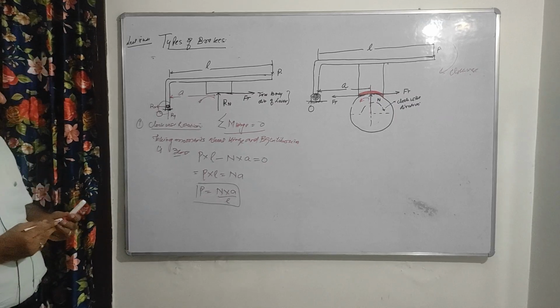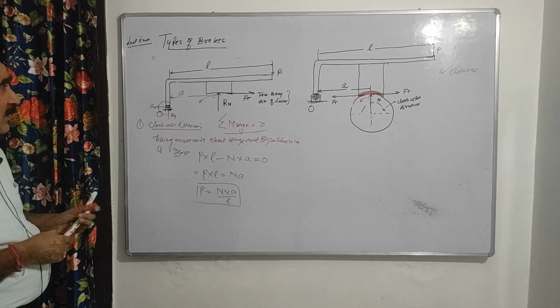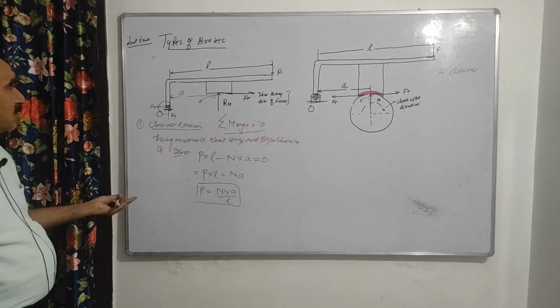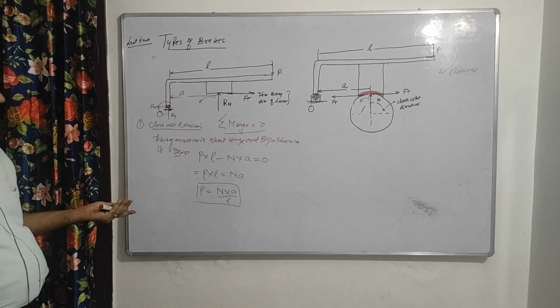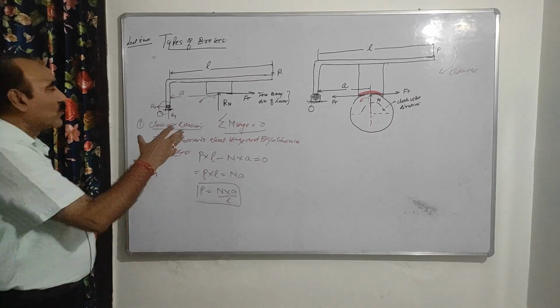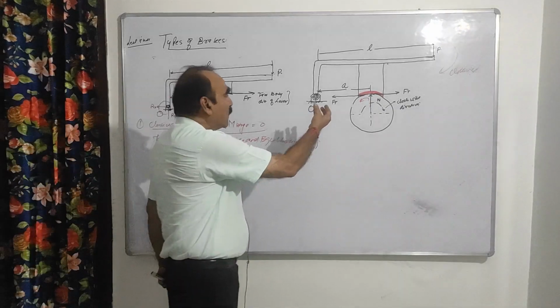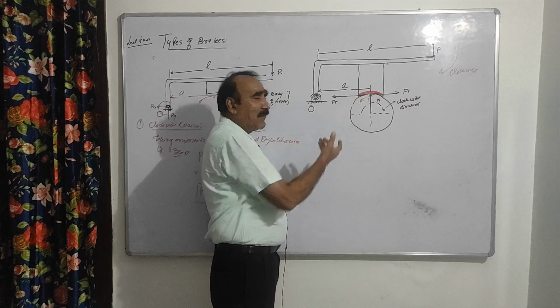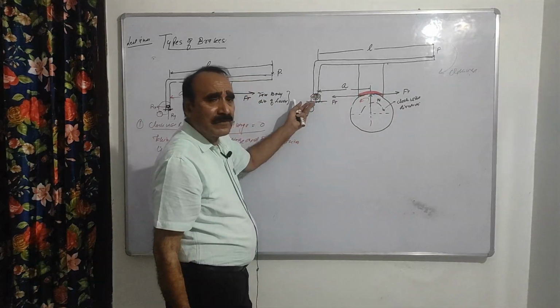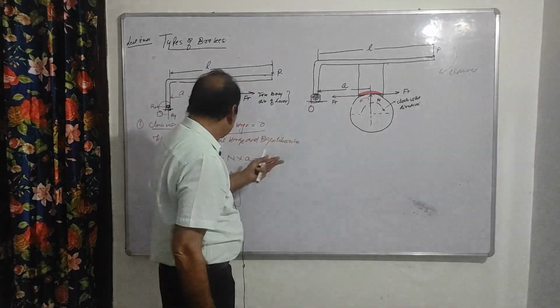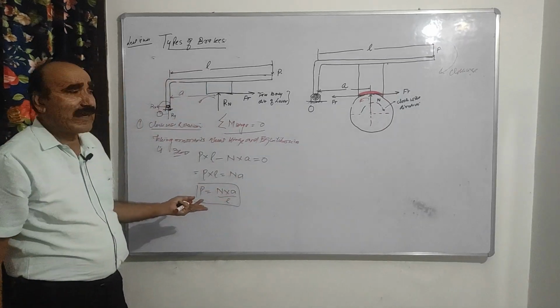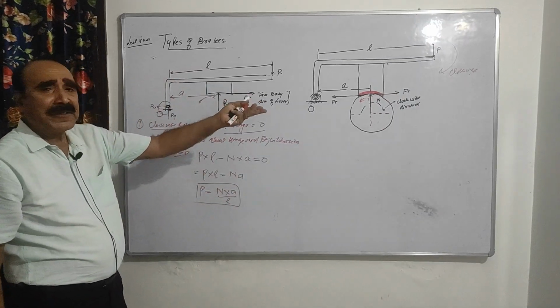When it is rotating clockwise, right? So the same condition applies when it is rotating anti-clockwise. Only the change, where will the change happen? Only the change will happen in this frictional force. But the frictional force is passing through the hinge. So the design equation will have no change, because when we take the moment about the hinge, the frictional force does not contribute.